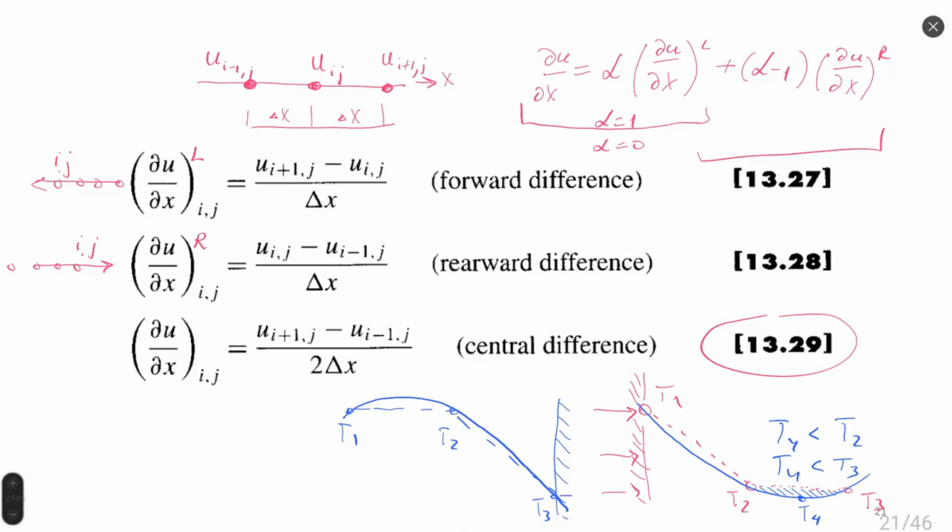So if I start to cool, I extract energy from temperature 3. By approximation with the parabolic function, we have an increase of temperature between point 1 and 2, which is totally wrong. It cannot happen. By extracting energy, you cannot increase temperature at any specific point. This is a non-physical solution. This is happening only because we substitute the time derivative in our equation of heat transfer in a wrong way, let's say, not by a wrong function, because there are methods to compensate this problem.